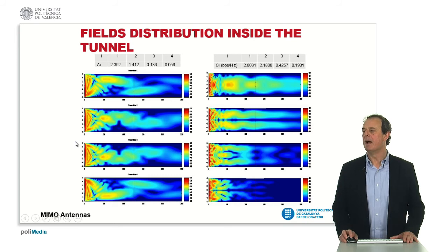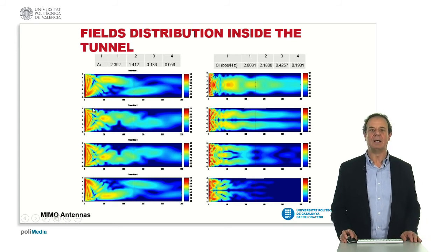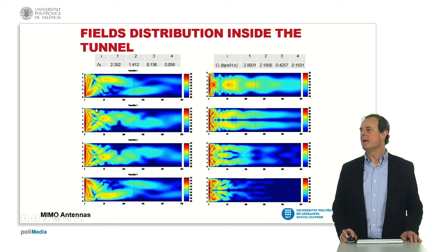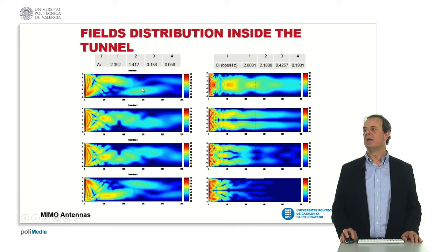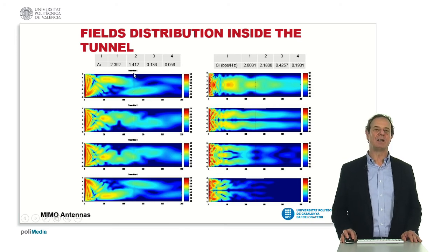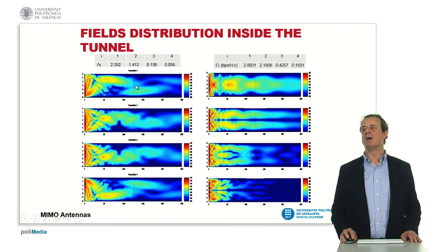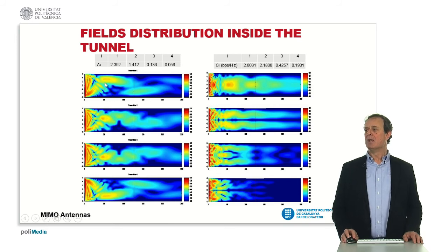So when we do this, on your left hand, you may see the real field strength representation as a function of the distance from 0 to 300 meters. We were interested in getting a coverage distance of at least 250 meters. So this line represents 250 meters. So that's the signal we get produced by each of the transmitting antennas.